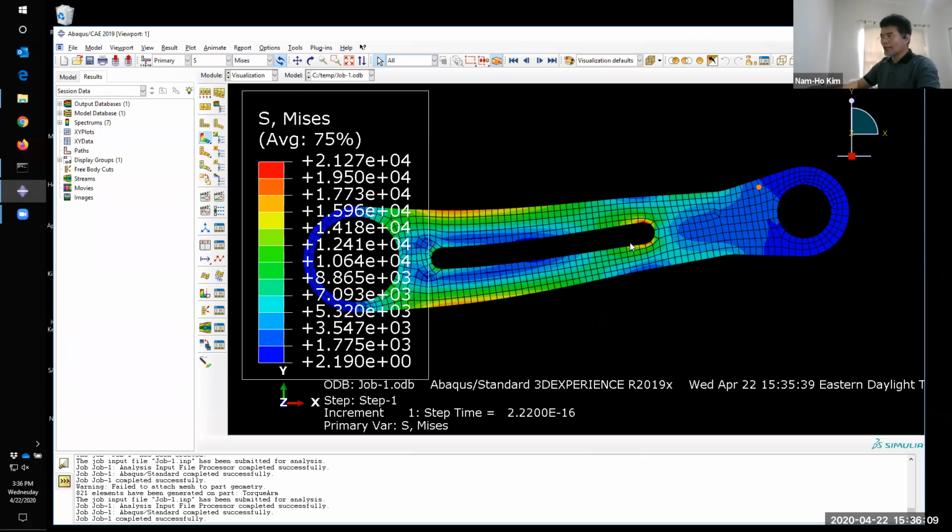Why? Because if the center cutout is small, then overall the part behaves like a beam. But if this one gets longer, then the entire thing becomes more like a box beam. So that's why the shear modes come in as you increase the inner cutout size.